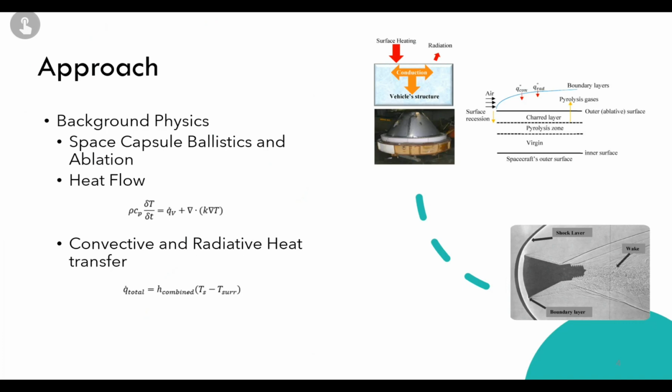However, the heating loads that we're dealing with are still significant enough where we need a thermal protection system. And that's where the PICA material comes into play because it is a very good defense against this heat energy. And there are some figures in the top right that illustrate how PICA absorbs and re-radiates heat and insulates the inner surface of the tile.